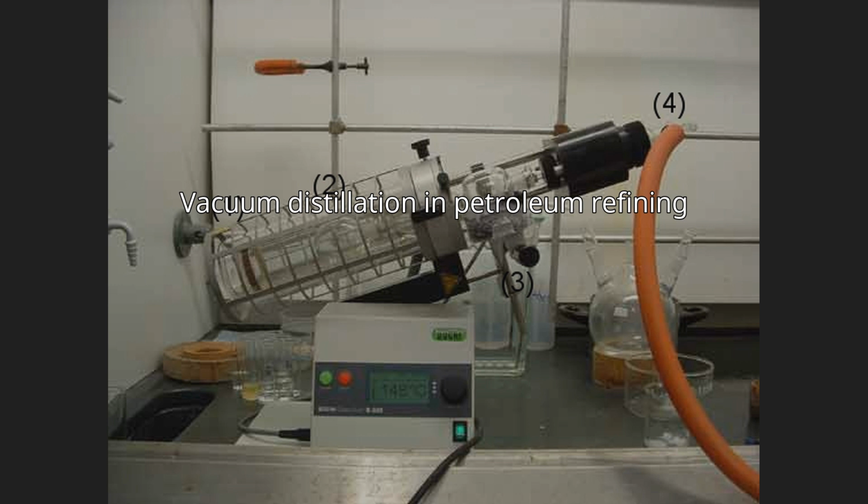Vacuum distillation can also be referred to as low-temperature distillation. In distilling the crude oil, it is important not to subject the crude oil to temperatures above 370 to 380 deg C because high molecular weight components in the crude oil will undergo thermal cracking and form petroleum coke at temperatures above that. Formation of coke would result in plugging the tubes in the furnace that heats the feed stream to the crude oil distillation column.